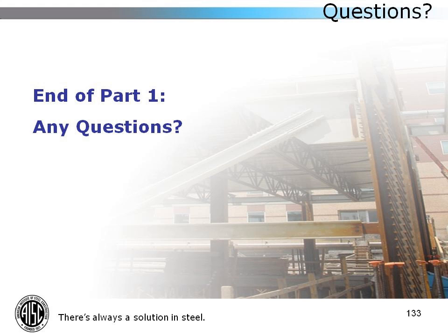You're going to have to use steel anchors, embedded plates, or you're going to have to apply the forces to both members concurrently to really be able to achieve the composite action you're looking for, because bond is just so variable. The tests do recognize the fact that the more eccentricity you put on the connection, the more strength you get because of the mechanical interlock. So you actually can develop the full plastic capacity of a filled tube without shear studs and bending. But if you're looking at straight axial compression, you're probably going to need to provide some means of positive transfer.